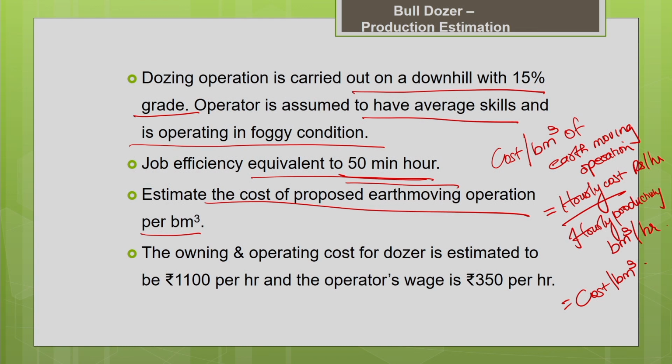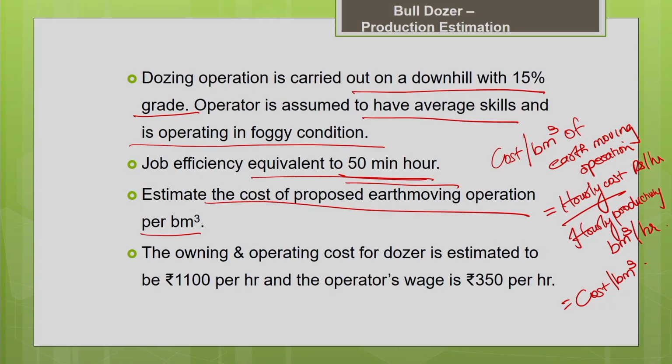This is a very important parameter which we use when we plan for a bid. When you go for unit rate contracts, you need to know the unit cost associated with every activity. We need to make an accurate estimation of the unit cost of every activity. For that you need the information on the cost associated with the machine and the productivity of the machine.